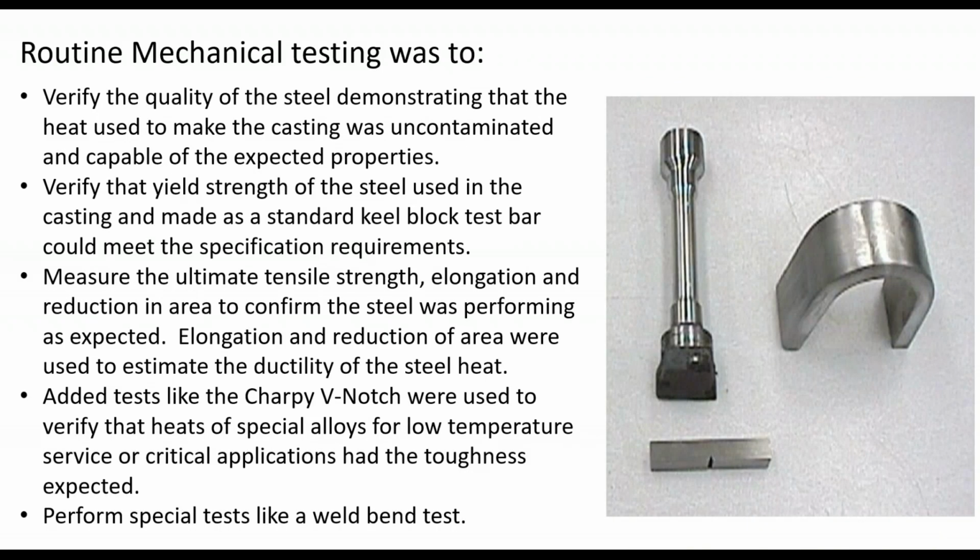So our routine mechanical testing was really intended to verify that the steel heat we made in the furnace was uncontaminated and had the right composition, the right quality in terms of low levels of sulfur and oxygen, that it could meet all of our expected properties. And so we would verify that the yield strength of the steel that was used in the casting, not in the casting itself, but of the steel that was used to make the casting and that made that standard keel block, could meet all of the specification requirements.